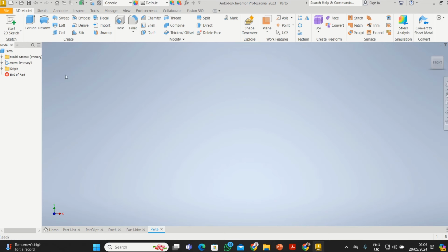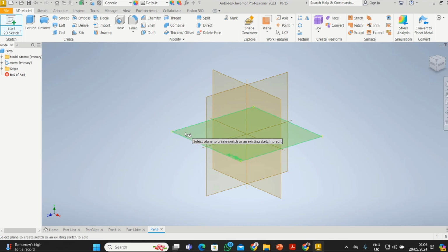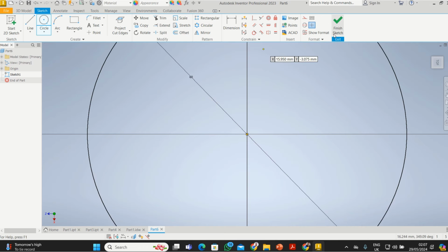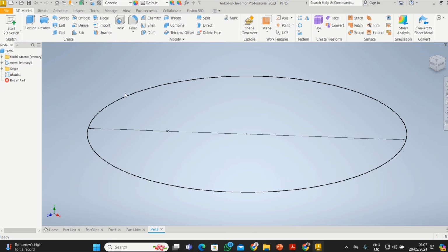So the first thing we do is to create our sketch. Select your plane where the sketch should be created. Okay, so you are looking at two cylinders of equal diameter, 60 mm. The major cylinder has a length of 90 mm, and the second has a length of 75 mm. So that's what we are doing. Let's create our sketch on the plane. Okay, let's make it 60 mm. So here we go. You can finish your sketch and then